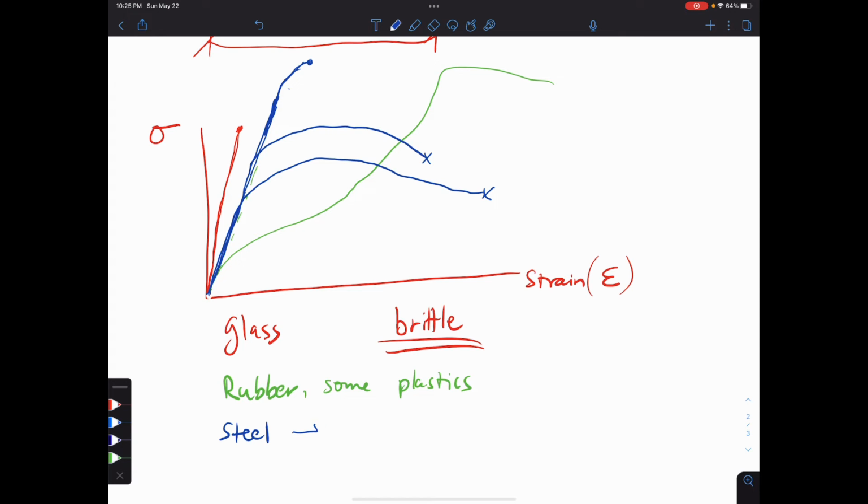So steel can vary. I'm going to give you some numbers here. Steel, the sort of super average, generally weak steel that you might just use if you went down to Home Depot and bought a piece of rebar or angle iron, might be 36,000 pounds per square inch, which, remember, we call PSI. Now that means that's the yield strength. Yield, okay? So that might be this one right here at 36, okay?